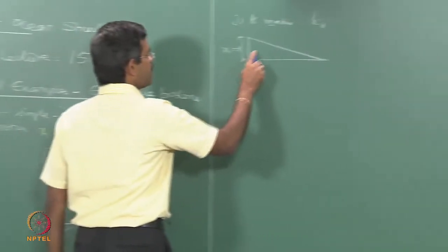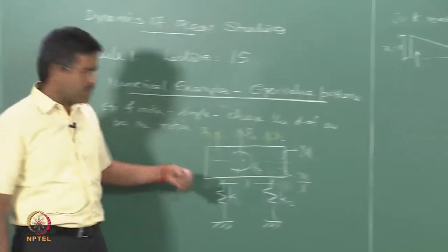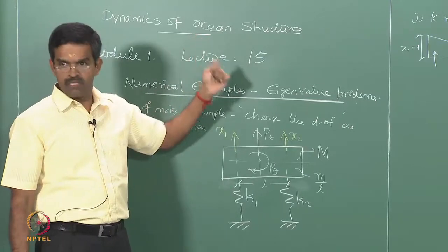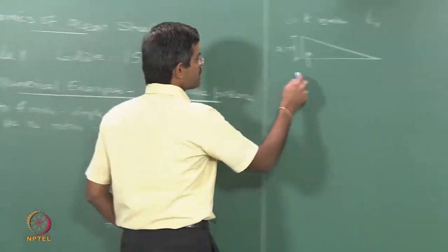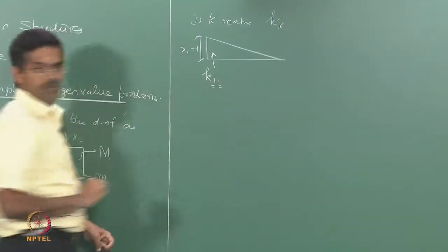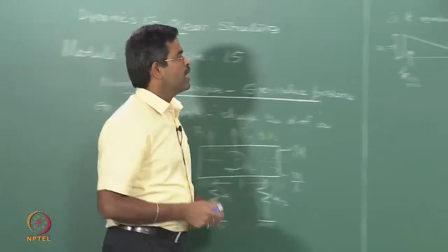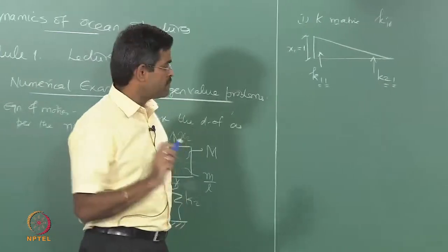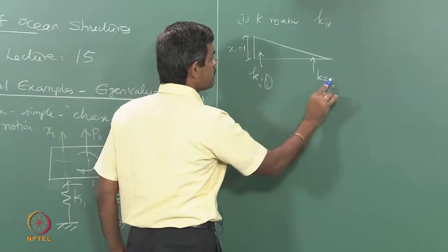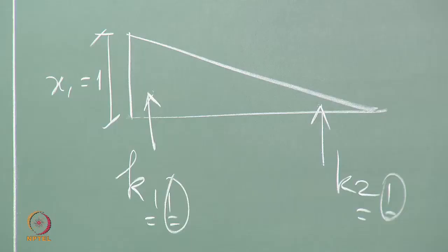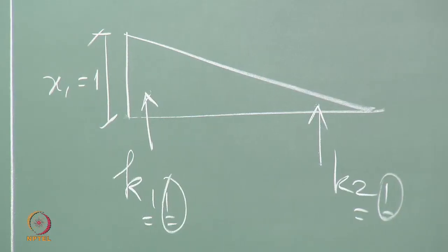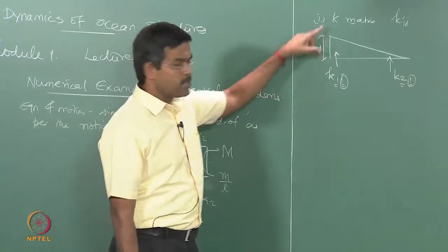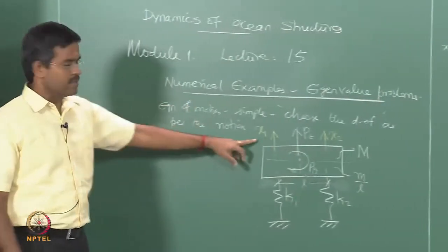So, the force will be applied vertically in the same direction because I want to apply this displacement, I must pull the spring up. Okay. I must pull the spring up to give this displacement, otherwise I cannot give this displacement x1 up, right. So, I should say this as my K11, row first column next, and I must get this as my K21, row first column next. Remember, the stiffness matrix is always derived column wise. Okay, you are giving displacement in the first degree, getting the force on all other degrees 1, 2, 3, 4, etc., but the second subscript will always remain 1 because you are giving unit displacement at the first degree. The first degree is here.